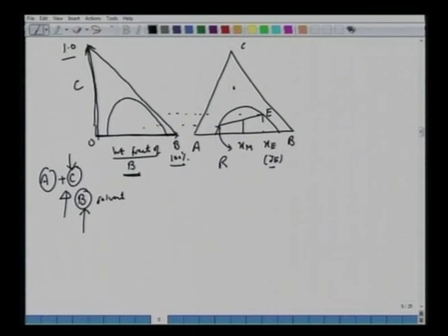Still you have the phase diagram, you have a tie line, so you have extended this here as extract. You take this, extend all this all the way till here, you have this tie line. You have this M as this. So this will also work as a representation of this extraction system with this as raffinate phase here. Here you will have extract phase, you will have XR, you have XC, except now the amount of A we have to calculate from 1 minus whatever B you have, whatever C you have here.